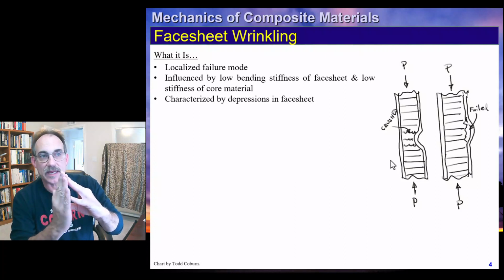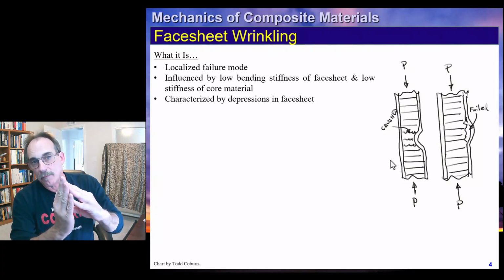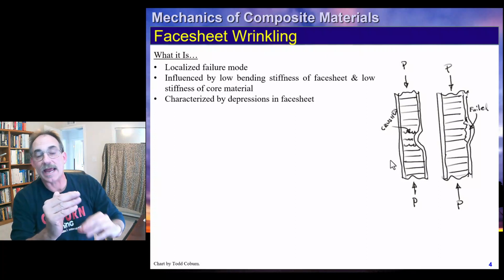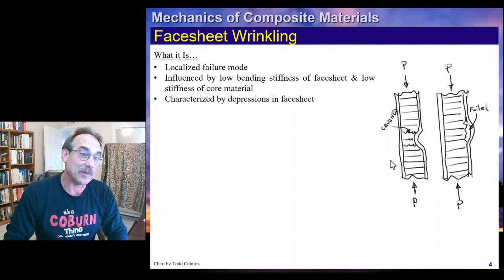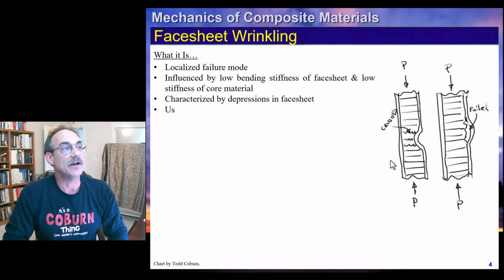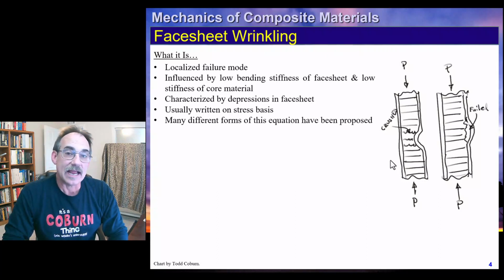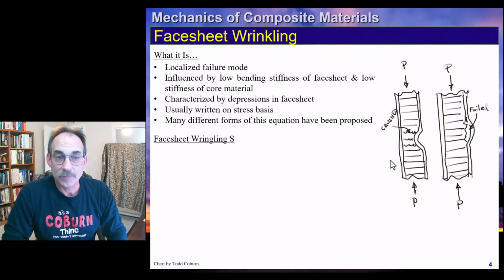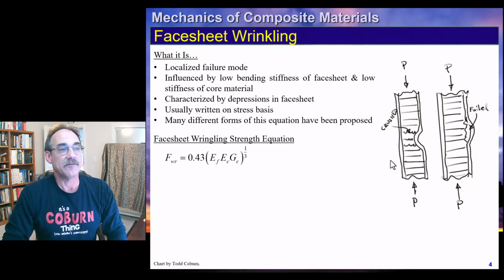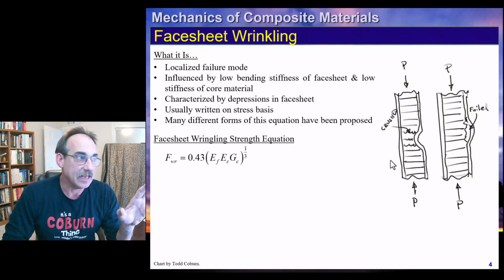It just needs to be pulling away such that the face sheet can continue to deflect, and that will eventually cause a failure as well. We usually write these on a stress basis, and I have experienced a number of different ways to develop this from many different resources, including some that folks that I work with have developed. I'm going to go ahead and present this equation from Brune, which is